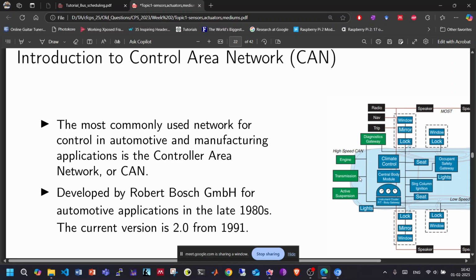When you are following a bus architecture, basically two signals are ANDed and then they are transmitted, right? Makes sense? So due to this nature, usually the dominant state is marked with 0 and the recessive state is marked with 1. Okay?